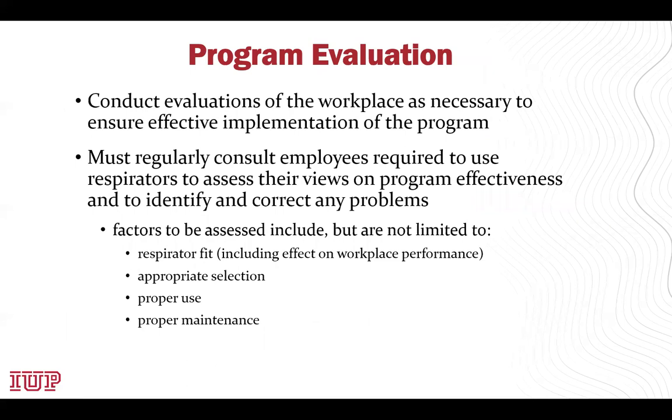Program evaluation. Conduct evaluations in the workplace as necessary to ensure effective implementation of the program. Must regularly consult employees required to use respirators to assess their views on program effectiveness and to identify and correct any problems. Factors to be assessed include, but are not limited to, respirator fit, including the effects on workplace performance, appropriate selection, proper use, and proper maintenance.